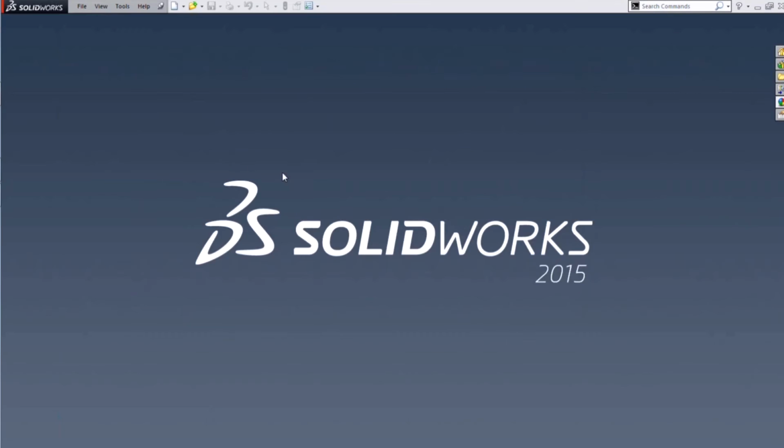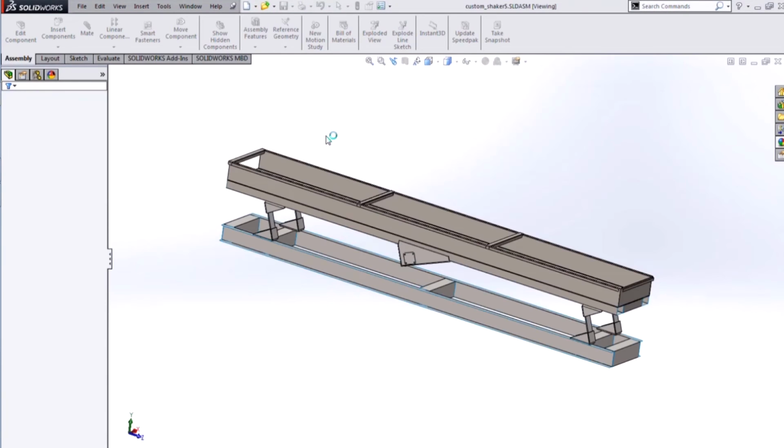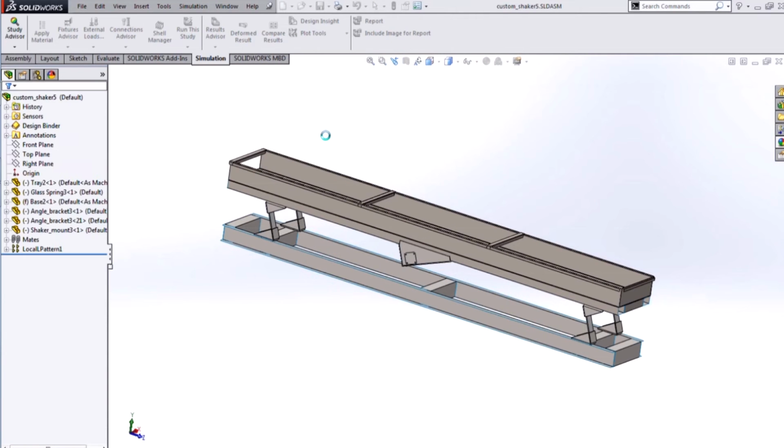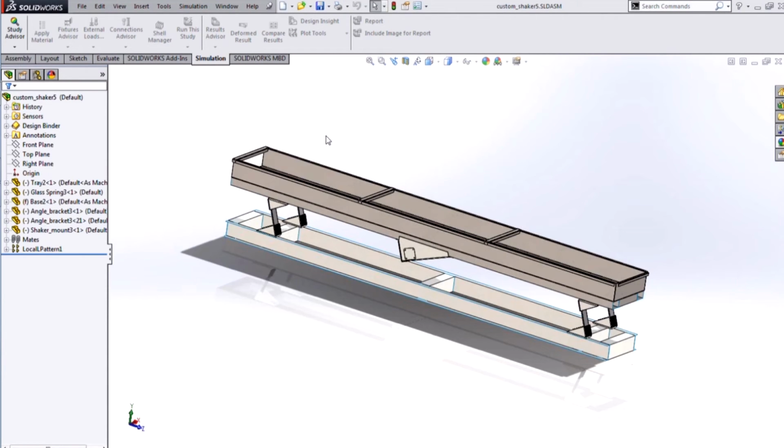The last enhancement I want to talk about in SOLIDWORKS Simulation are some capabilities we've added for when you want to use shell mesh. If you're not familiar, shell mesh, which is also referred to as shell elements from a technical standpoint, is a mesh type that's commonly used for thin geometry, things like sheet metal parts, because it's a much easier way to represent the geometry and get good results of your analysis without as much meshing or solve time.